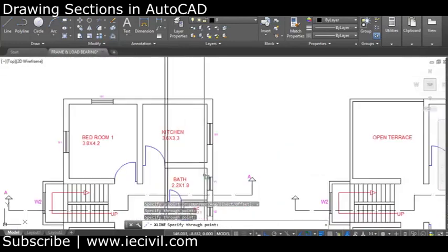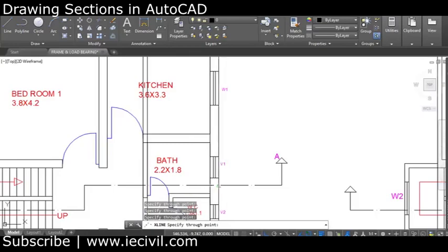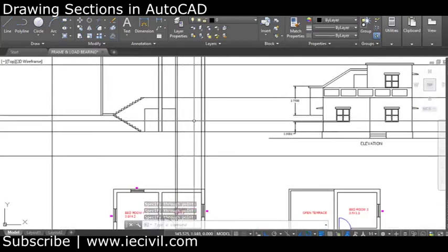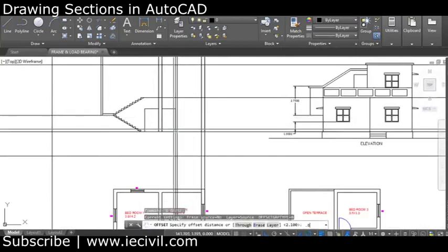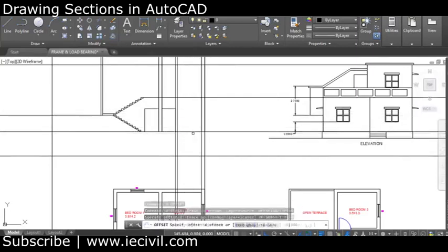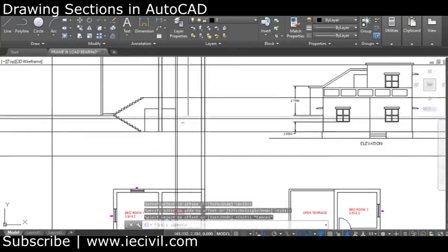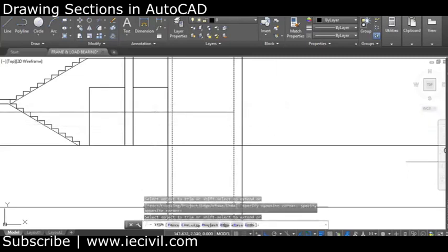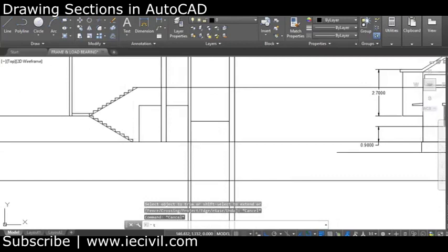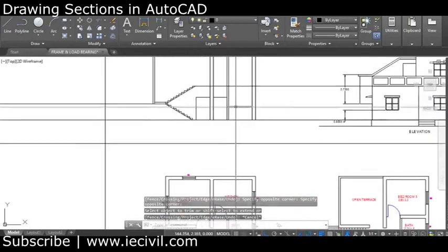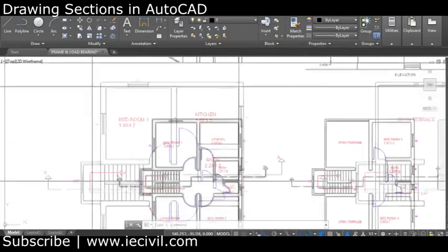Okay, this is done, and now the exterior walls. So the wall is ready, and I suppose my dado is around 800 mm, so 0.8 from the ground level. Okay, that's quite small. I'll take it 1.2 meters from the ground level. So this is the dado that will be visible from inside over here, and this is the wall.